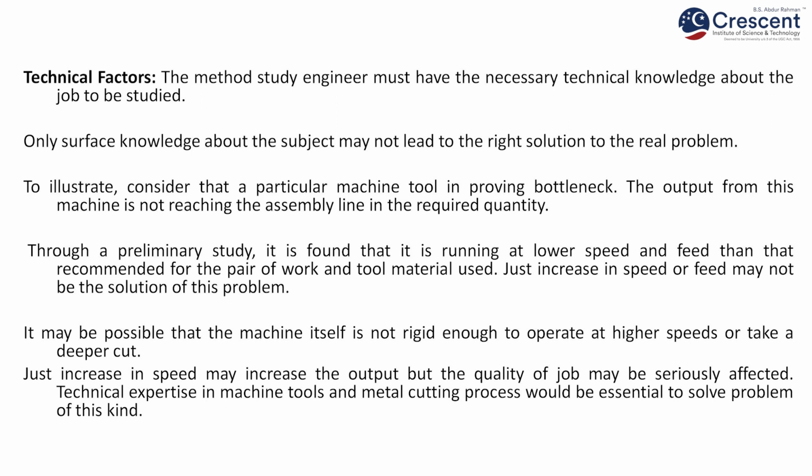For example, in one production line bottlenecking is there. From initial investigation we can find a slow operation in one station. Maybe if we increase the speed, okay, but some operations have inherent characteristics such that we cannot increase the speed, like threading or milling. If we increase the speed, there is quality loss and the whole production will be rejected. So, we have to understand the root cause behind the problem and then solve it.